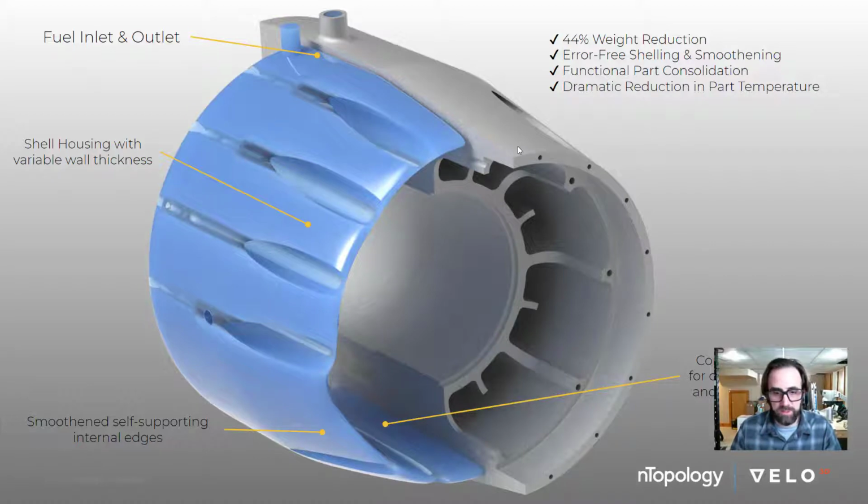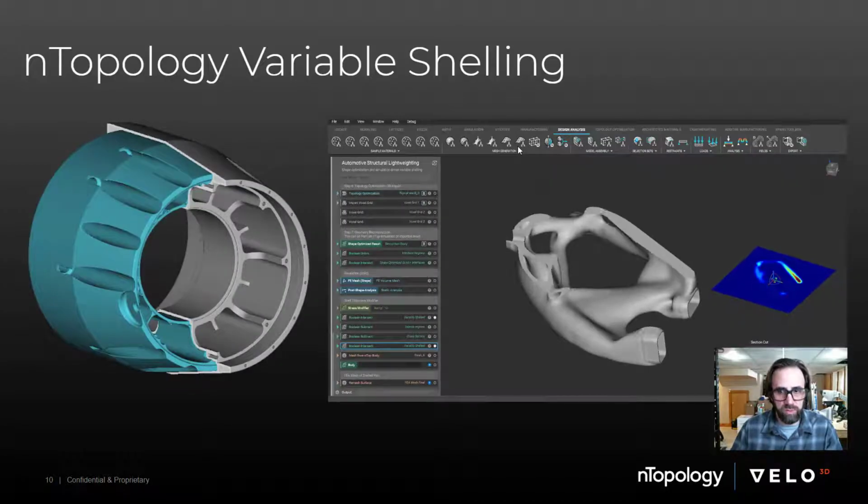So for an aerospace application, if it was going to be a flying generator, we wanted to add the cooling so that in this scenario, they would actually use fluid, in this case the fuel, to preheat the fuel. By preheating the fuel, they're going to get advanced combustion efficiency. In addition, they're going to keep their generator cooler, so they'll get even higher efficiency. I'm going to quickly go over how we implemented that.